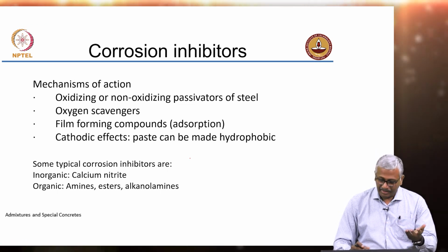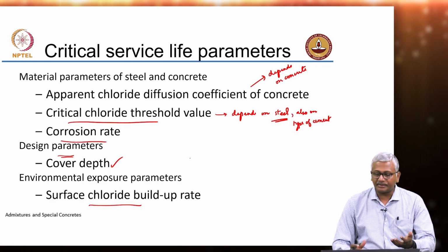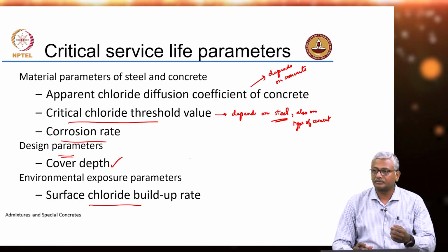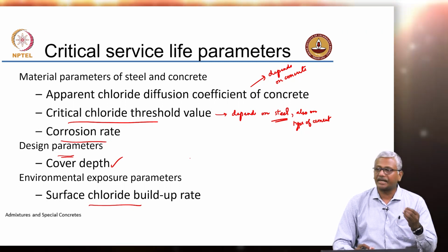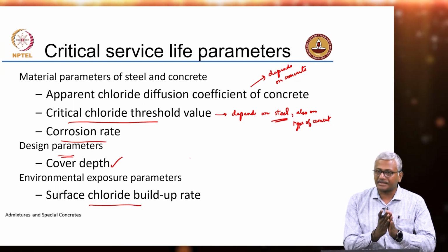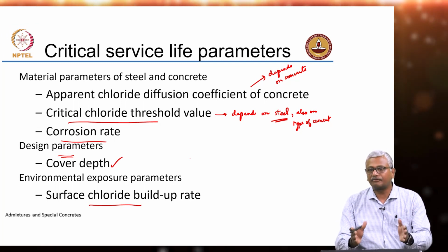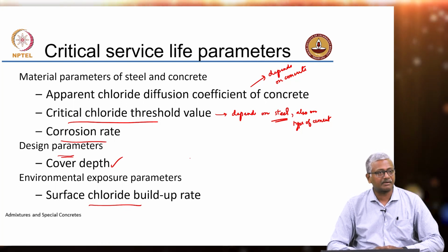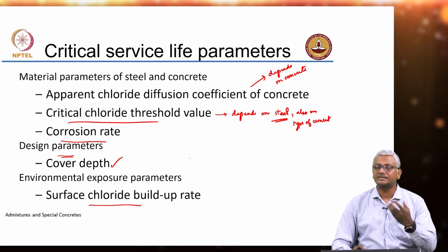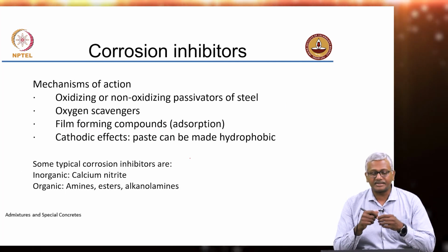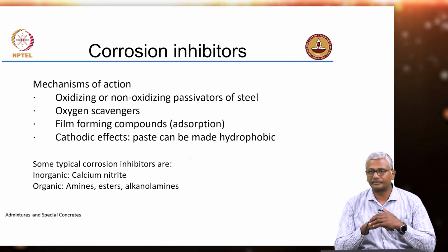Now, where all of these things really make a difference is in the material selection process. So, you need to select your materials appropriately to ensure that you are extending that initiation phase after understanding how all of these characteristics are making a difference to the service life. So, here what we want to do is enhance the corrosion resistance by utilizing corrosion inhibitors.